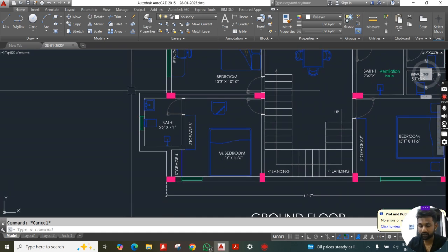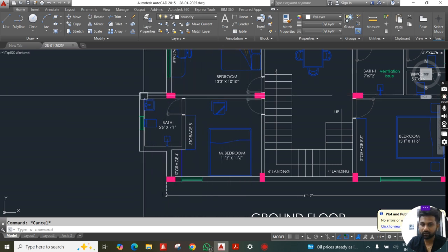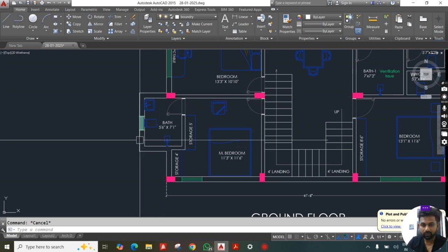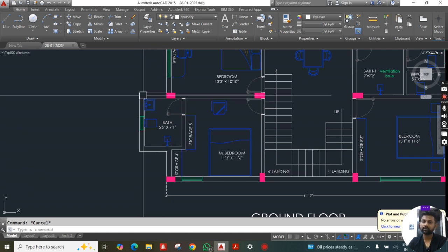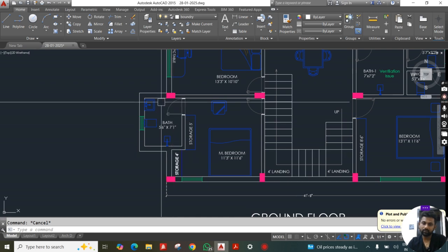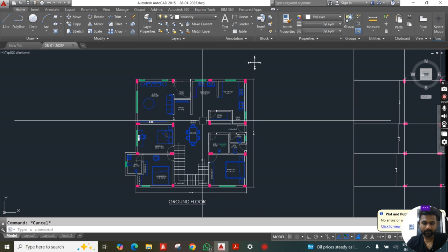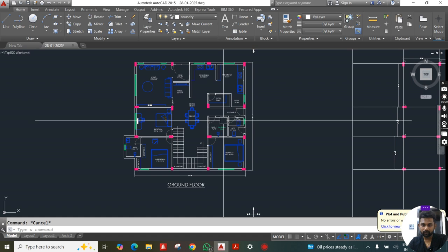What happens in a practical scenario is, you already have this plinth beam, and it just gets continued here. You already have this beam here, and you will just have an L shape of beam here, that's it. That is the plinth beam. It's getting connected to this plinth beam and to this plinth beam. Anyways, I'll show you the side. We'll be going up for the layout for this building also.